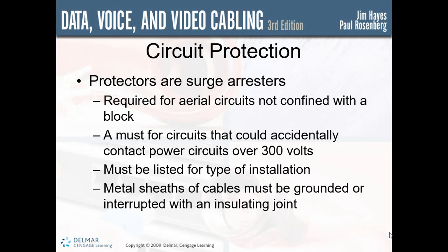Grounding electrodes for communications ground may be any of the following. You can use the grounding electrode of any electrical power system, grounded interior metal piping, metal power service raceway, or power service equipment enclosures. If the building being served has no grounding electrode system, then you have to have any acceptable power system grounding electrode that's covered under the NEC sections, a grounded metal structure, or a ground rod or pipe at least 5 feet long and a half-inch in diameter driven into damp ground or damp earth. If possible, it must be kept separate from any lightning protection as well.